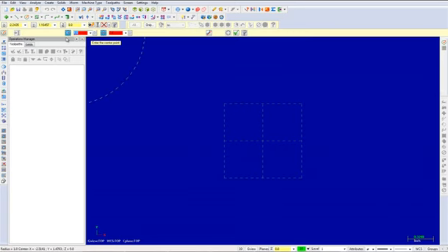From here, choose the Fast Point command and enter the following coordinates: -1.25, 0. Once complete, press the Apply button to continue. Press Enter. Now choose the Apply button to stay within the command. To view the entire geometry, select the Fit icon.